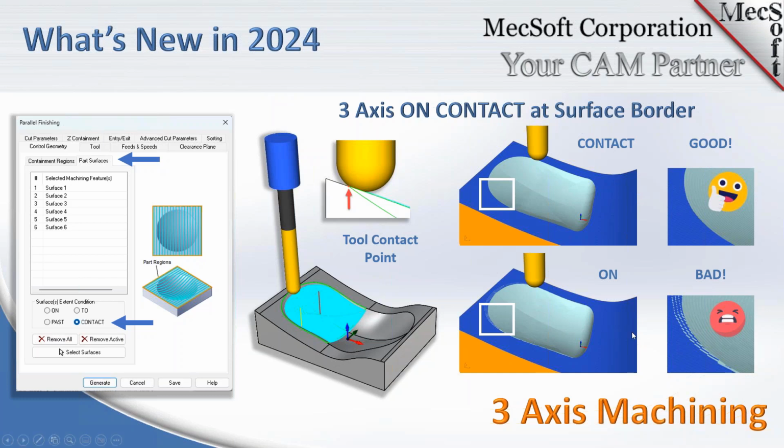In version 23, the default condition was the on condition, meaning that, and I'm going to show this a little better in the part file demo, in the on condition, when the tool axis and the tip of the tool aligned itself with the perimeter curve that you're machining, it would stop. And for parts that have cavities, the tool is actually rolling up over the parting line, which is a big no-no. Tool makers do not like to see that tool ride that parting line.